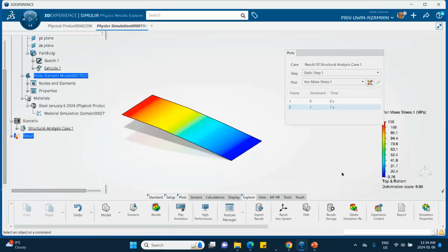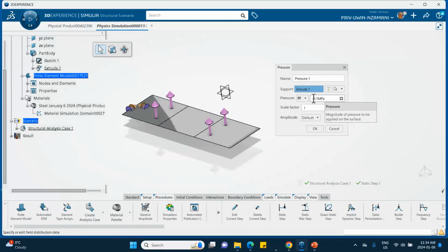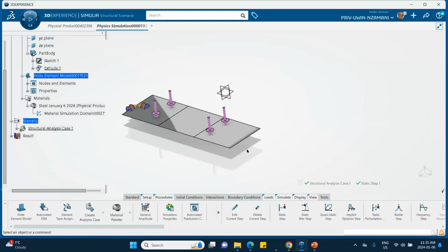Go down, down. And finally, if you go back here and go to the pressure and take this minus away, notice that the pressure is applied at the bottom side. We took the minus away. Bottom side, the blue is at the bottom. A positive number means it's pushing into the blue. So this is going to go up now. It should go up. Blue is at the bottom.